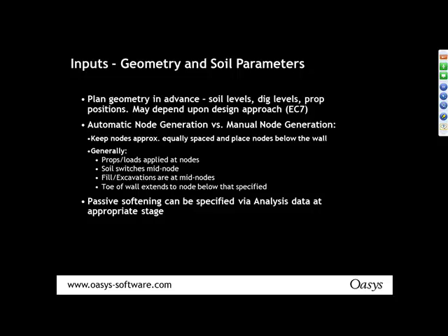Once you've done this, you also need to plan the geometry. And when I say plan the geometry, I mean, for example, if you're planning a construction sequence, what are the levels of dig? Where are the prop positions? And also, are you doing an SLS or ULS analysis? Because you may need to vary your dig levels, for example, if you're doing an EC7 analysis.